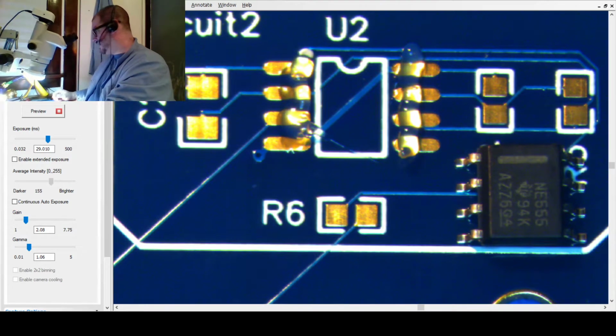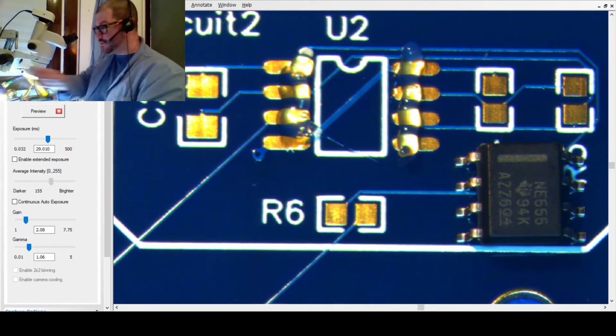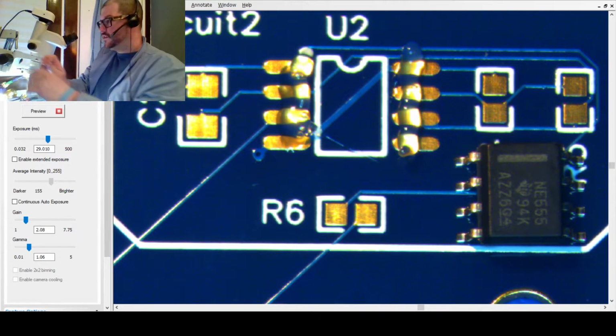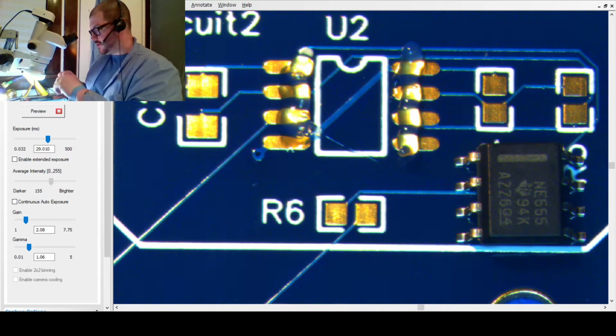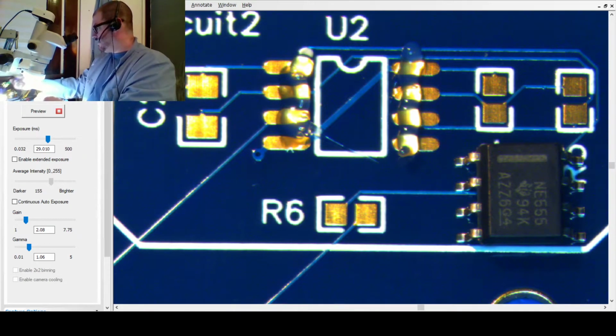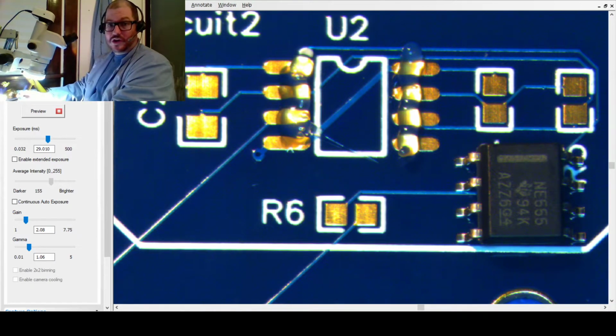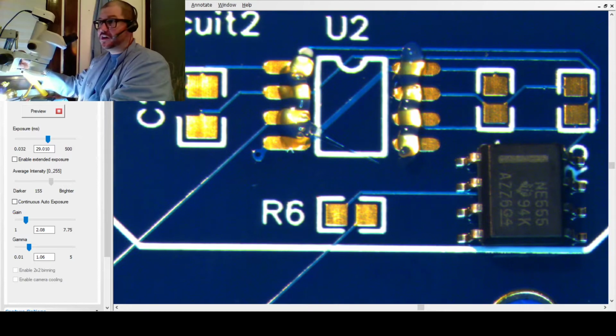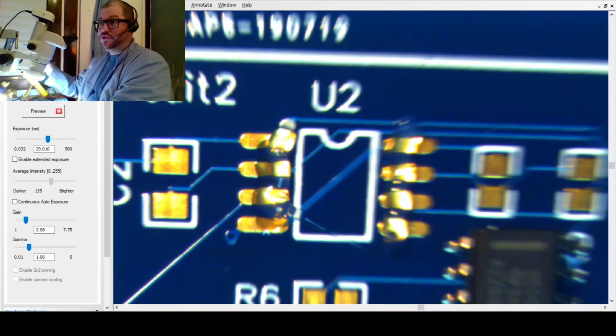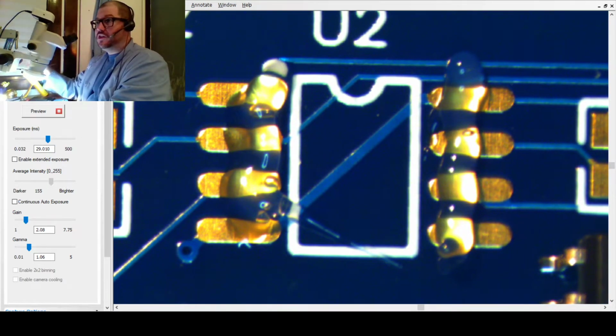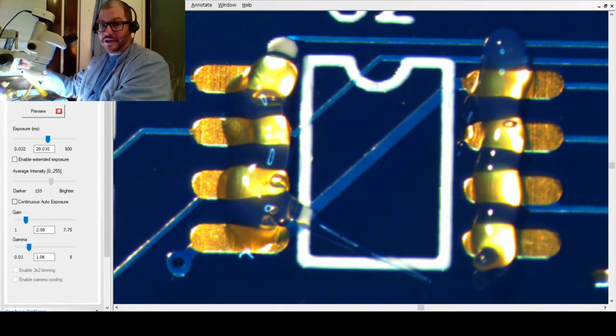And the next thing that I'm going to do is grab some solder off of my spool. There's some solder coming off of my spool here that I've got. And grab my large tip soldering iron. Now, I am going to tack down one of the pads of this chip. And I'm going to zoom in a little bit so you can all see, more or less, focus on the pads of this chip.